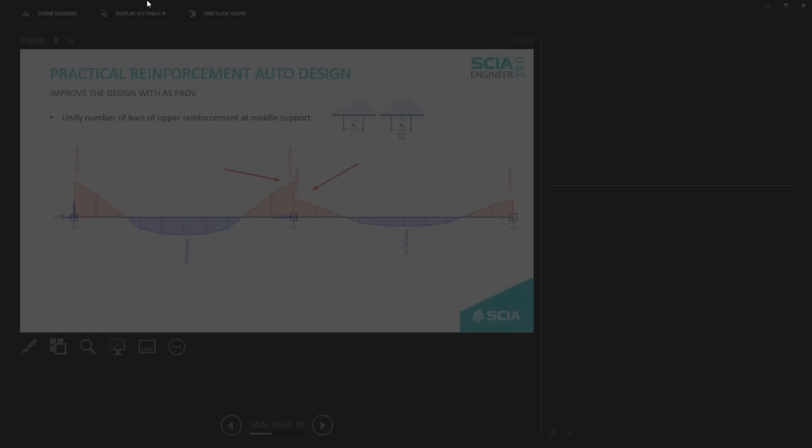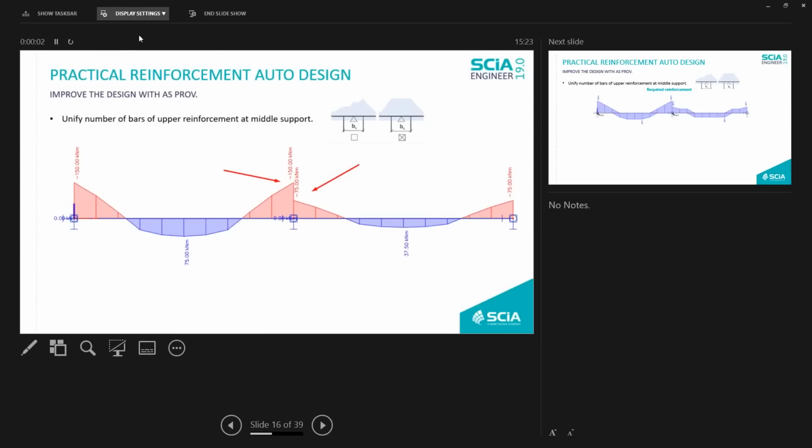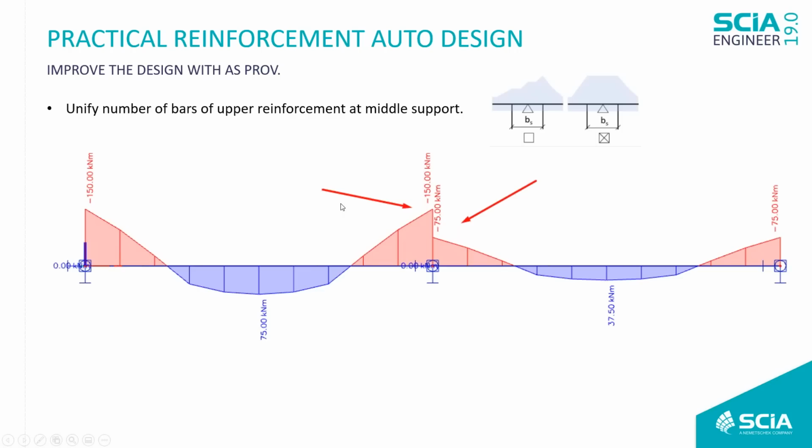I will continue now with the new advantage of the new version. Now it's not regarding the stirrups; it's regarding the longitudinal bar. Uniformity of the reinforcement above the support. In some cases, let me be more precise, you will get a bending moment from the right side not exactly like the bending moment from the left side, especially when you are modeling your beam as pieces. So I have modeled this piece from here to here, and then this piece from here to here.